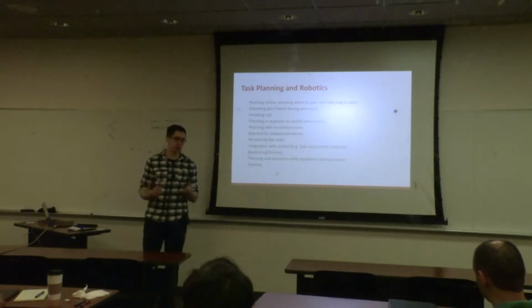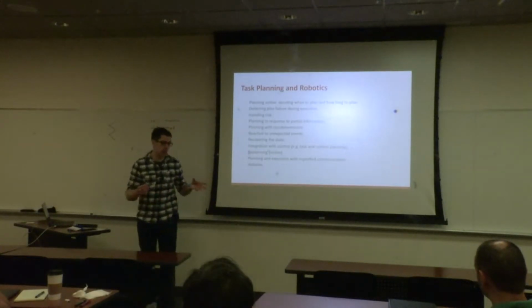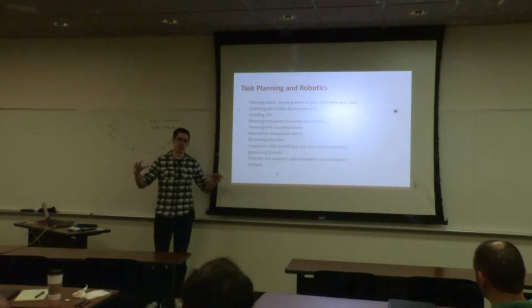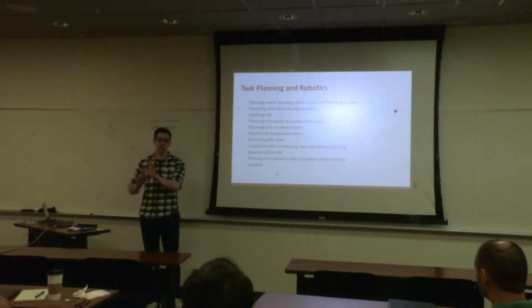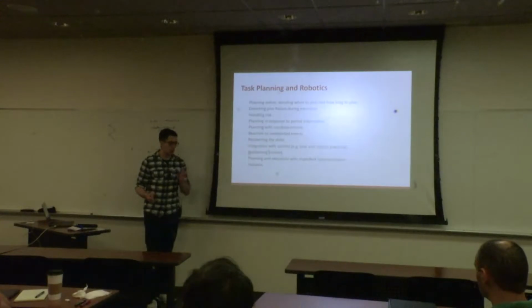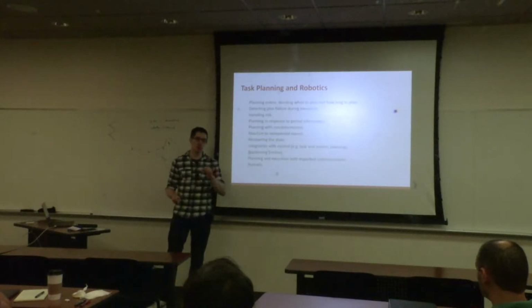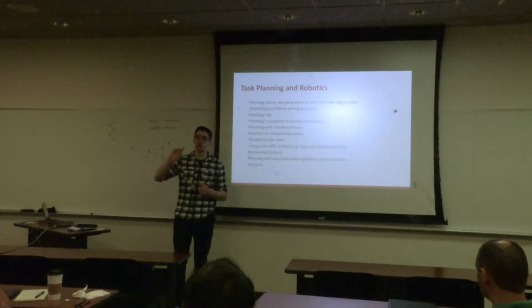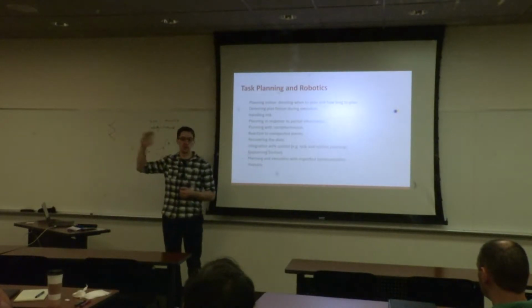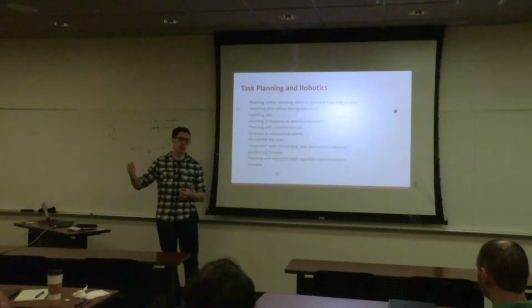So as an example, in the Pandora project, we would build a probabilistic roadmap around these large structures. In simulation, we would cause collapses where certain paths between the seabed structures would become obstructed. While the AUV was performing a maintenance or inspection mission, it would notice this obstruction. And sometimes that obstruction wouldn't invalidate the plan now, but would invalidate the plan in 2 hours, because in 2 hours' time we're going to pass through this point.